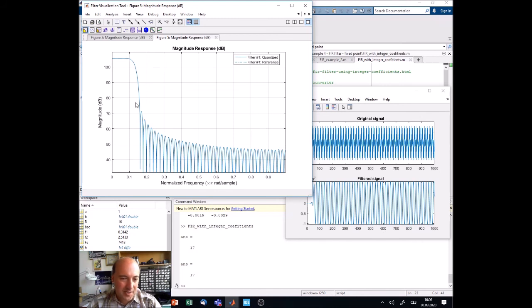You can see here that this is again a low pass filter. In this chart it's shown as a normalized frequency, in relation to the sampling frequency. This will be the part that will pass through the filter, and this will be blocked, and it will attenuate higher frequencies.